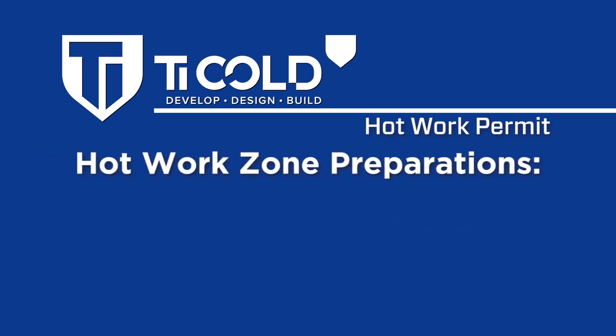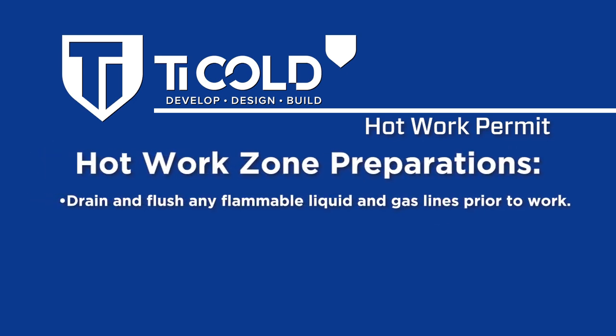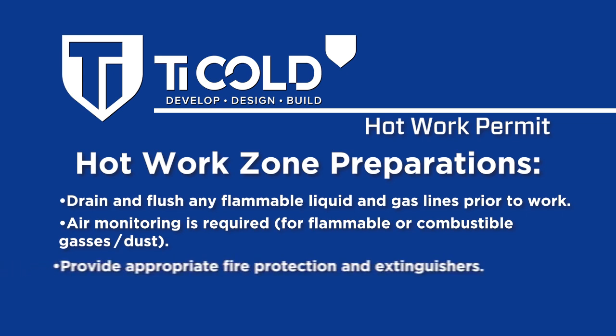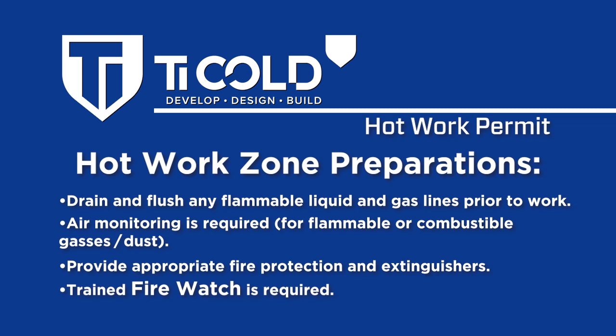Hot work zone preparations. Drain and flush any flammable liquid and gas lines prior to work. Air monitoring is required for flammable or combustible gases and dust. Provide appropriate fire protection and extinguishers. Trained fire watch is required.